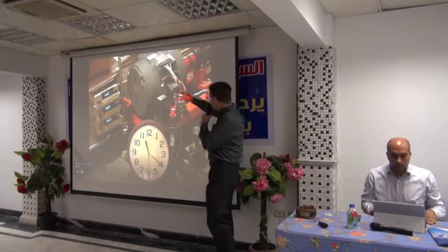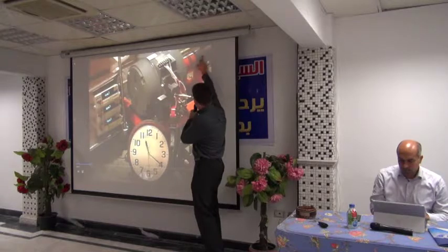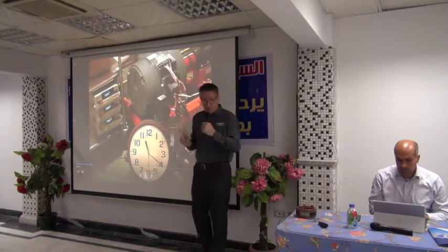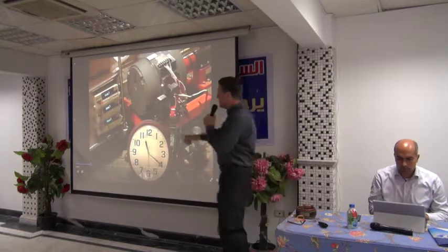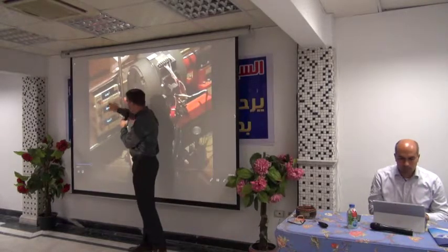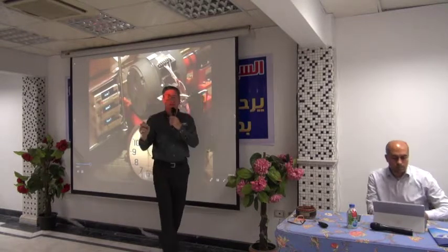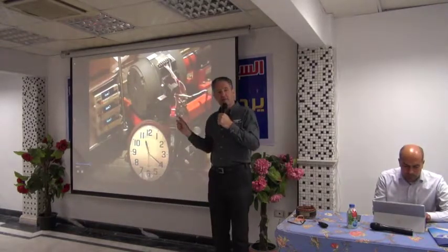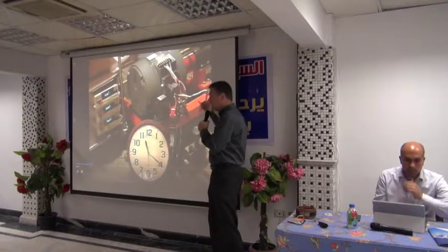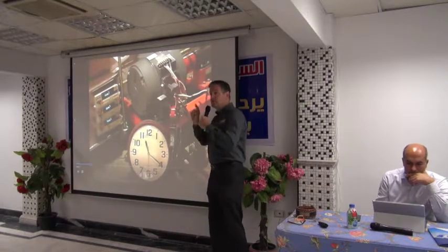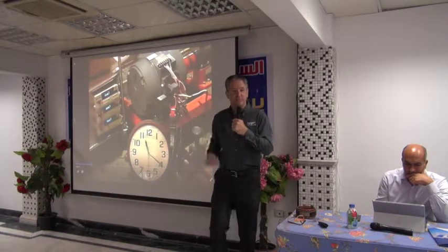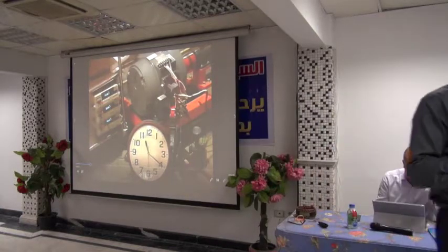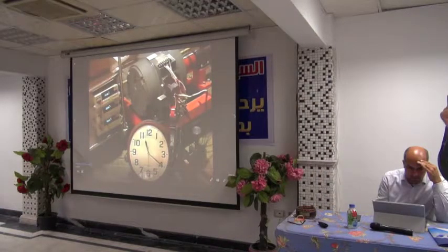Okay? The motor is being load tested. Here is a coupling, here is a load. So the motor is running at 100% load. Okay? We're measuring the three-phase currents here, making sure we have balance. Okay? And in the video, when I run the video, you will see someone hit the switch, and when the switch closes, we have a short circuit inside the motor. And then we will see what happens. Okay? So this is really demonstrating what happens when the motor has a short circuit in your plants. What happens?